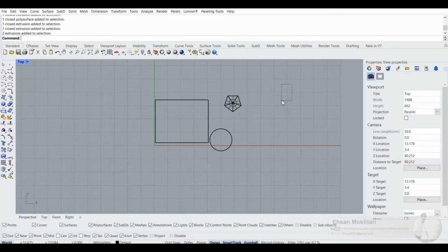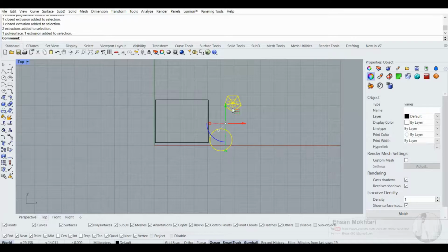With crossing selection, you can see its rectangle appears, but this time it is with a dashed border line. It's not a solid border line. So this dashed border line means that this is the crossing selection. This crossing selection will select all the objects that even touch the border of this selection area. So if it is inside, it will select. Even if it touches one object, it also selects the second one as well. So in this case, you can see it selects these two objects.